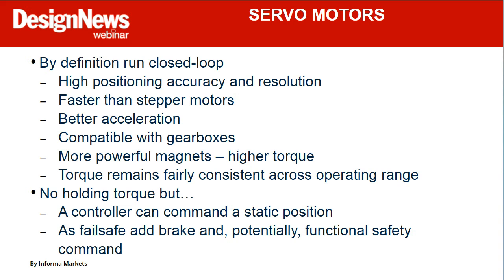Your motion is only going to be as good as the mechanical capabilities of your system. If you got slop in your system, a 24-bit encoder is only going to tell you, hey, I've got slop, and let's try for that spot again, and you're just going to dither. So within the bounds of the system, though, you can get very high accuracy and resolution.